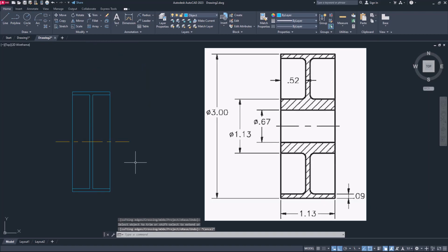Now we have given radius, right? We'll take it as 0.1. So F for fillet, R for radius, 0.1. Let's try to see. Again, repeat this. Okay. This time I will use multiple command. So command remains active like this. Okay. Now save your drawings.